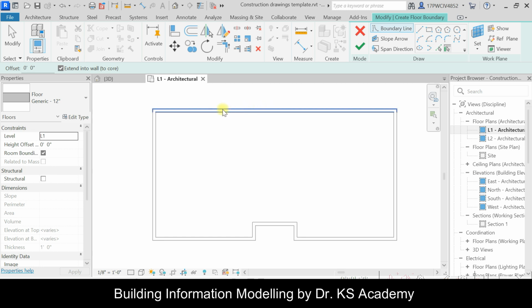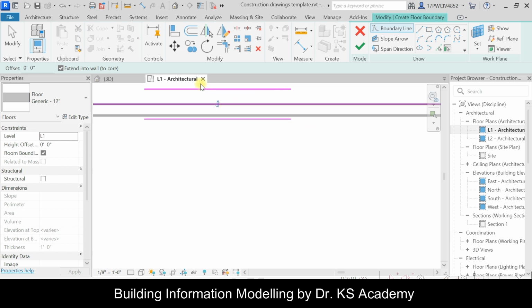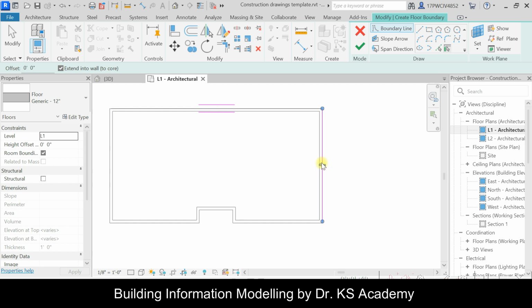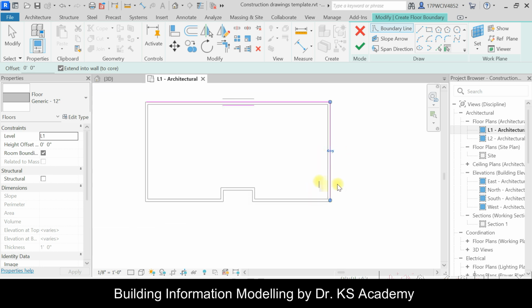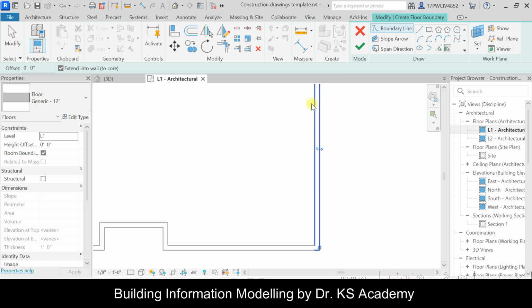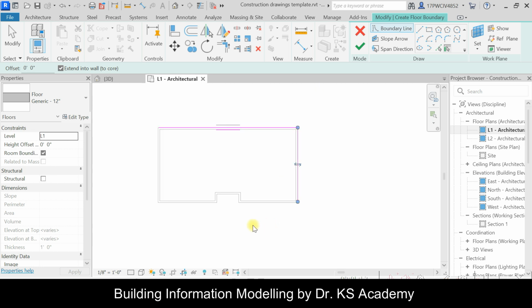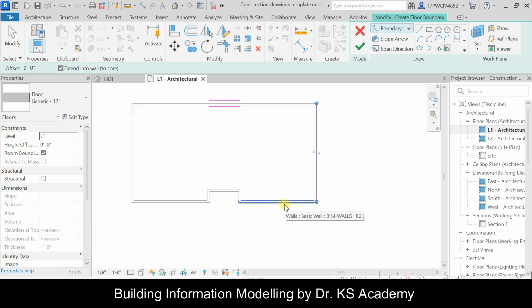What is the pick walls method? It means that for the walls we have created, I'll just click on this wall, and there you go, we have this pink line right below this exterior wall section. Similarly, I'll click on this one, and we have created a pink line on this exterior boundary of the wall. And similarly, I could select each one of them, but it will take some time. So the best trick is you highlight this wall, and from your keyboard you press tab.